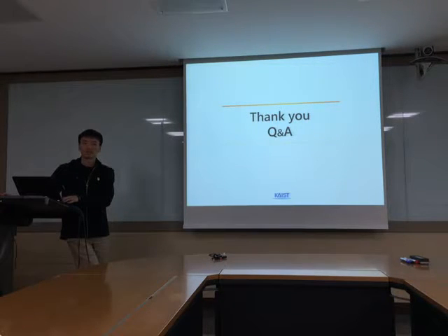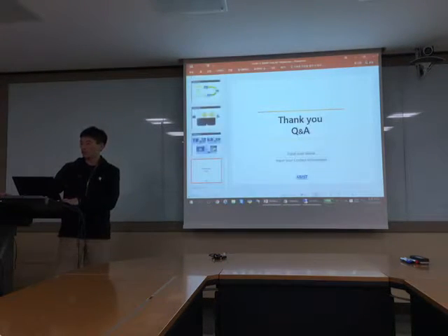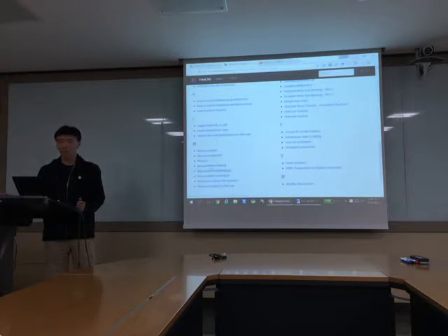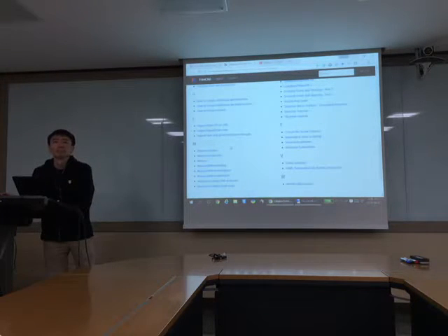Anything else? Thank you. You introduced the FreeCAD API. Should we use the API or just make a file? Yeah, you can use it. You check the command by clicking a button and looking at the console window, and use that command.